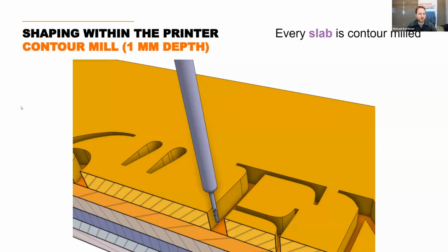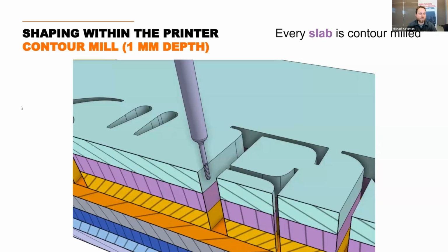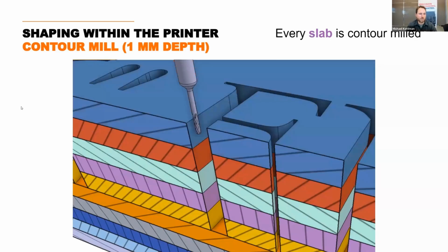Then when we finish that, we start printing the next layer. We do the refinement on that, and we can continue to step through, which lets us get that 6 thou ball end mill very deep into parts, which you wouldn't be able to do in a finished part or starting from raw material. That's what drives a lot of the use of sinker EDM for these features.